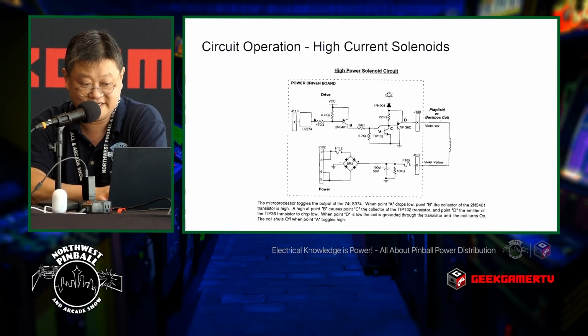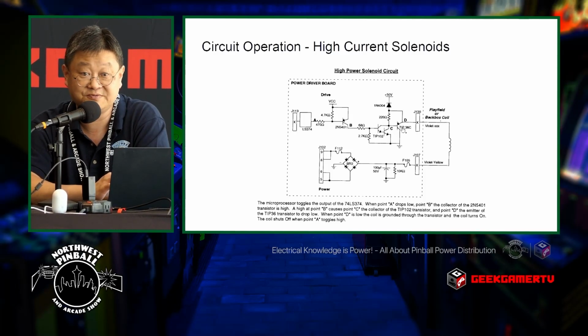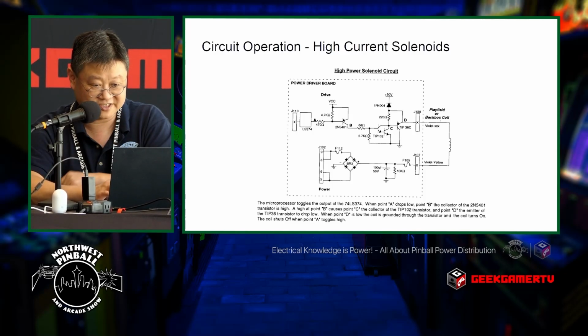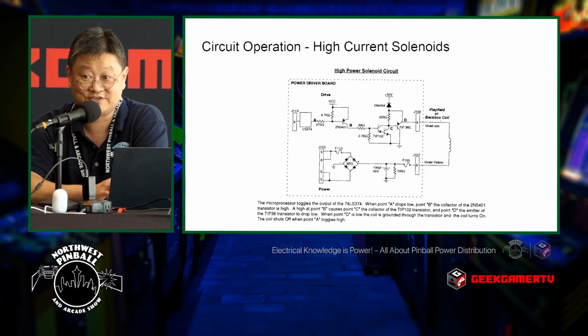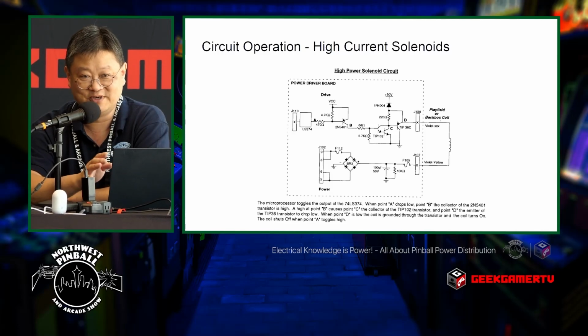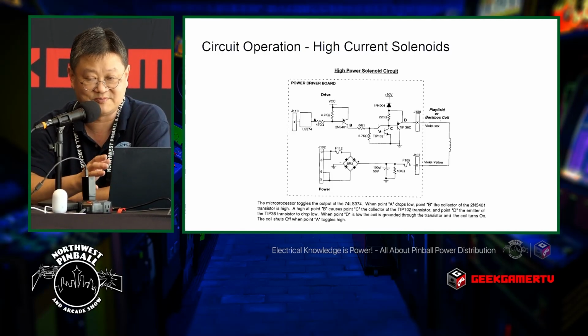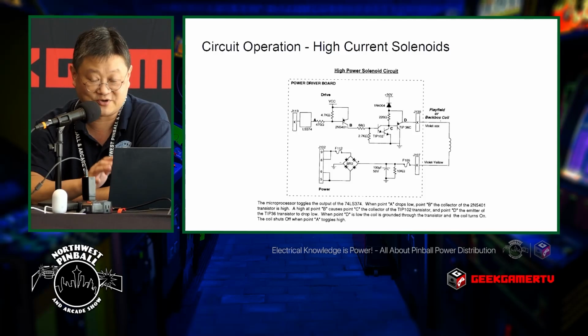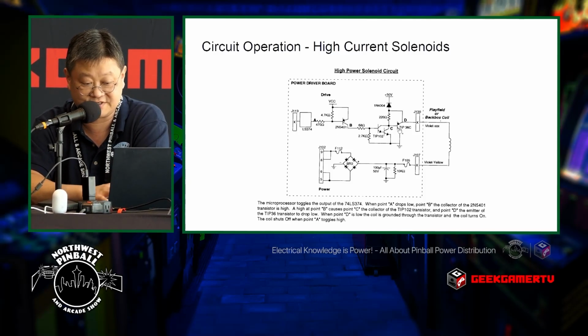And this here, this top part here is the path to ground. And it's kind of fancy, but essentially this transistor, this TIP36C here, acts as a switch. It's either on or it's off, and it's controlled by software purely digitally. You can actually bypass this by grounding the tab on the transistor that sometimes people will tell you to do. You can't actually do it with the TIP36C. But I know that some people have heard of it, you can actually ground that tab and you will bypass all of this control circuit.